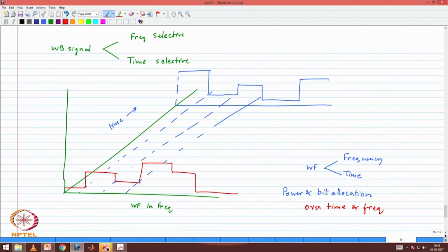You would do the power allocation, and this is exactly what 4G does. LTE system, multi-carrier, 1024 carriers. Each carrier, as a function of time, you adjust the power and the bit allocation, and the next time instant you keep changing it. So basically, this is how we achieve capacity in the cellular system. Okay, any questions?